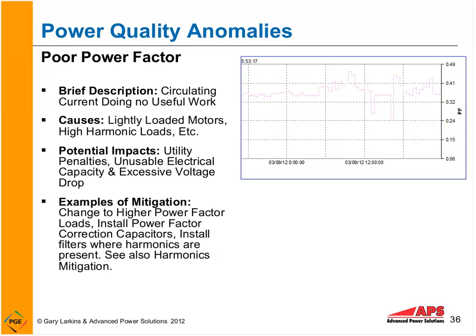Sometimes we have what's called poor power factor. We may receive a penalty for poor power factor. This does not necessarily cause malfunction of the loads out there, but it may cause overheating or a loss of capacity use of our electrical distribution system on our facility. So lightly loaded motors are a big cause of poor power factor, as are high harmonic loads, which we'll talk about.